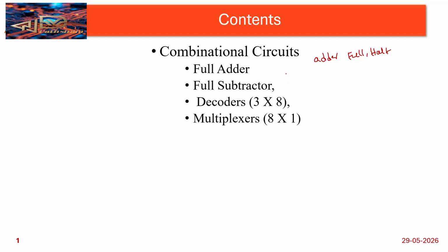One more thing, for enable signals, for example, select equal to 1, select equal to 0, can this be called an enable signal? That will also be called an enable signal, but sometimes we have, suppose this is a decoder, a 2 by 4 decoder. That means two inputs I am giving, those two inputs are A and B, and the enable signal means an extra pin is there.